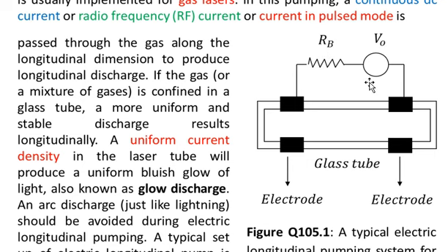It means that the voltage across the DC supply will now be reduced. If you keep on lowering the value of RB, you allow more current to flow, the voltage across the bias resistance will increase, and ultimately the voltage across the DC supply would decrease.